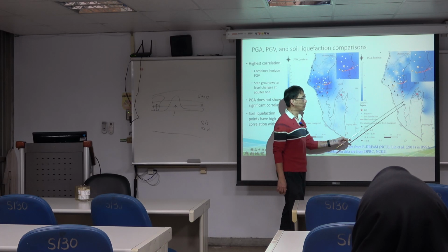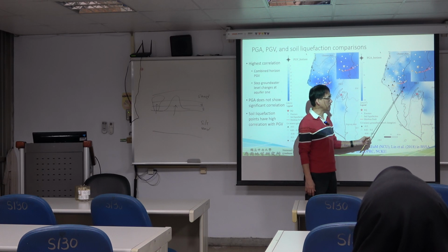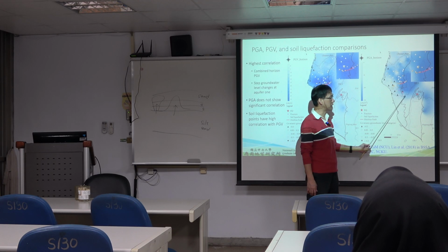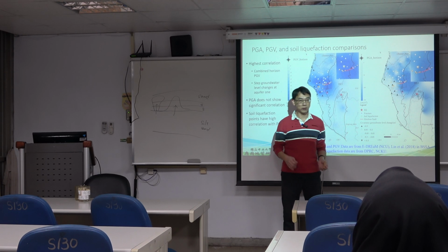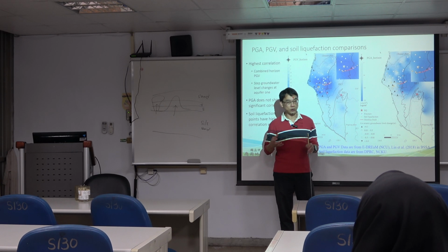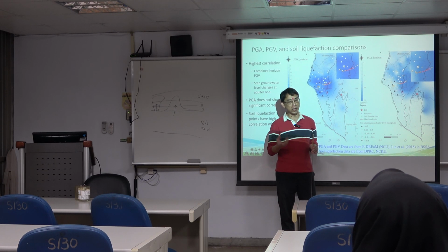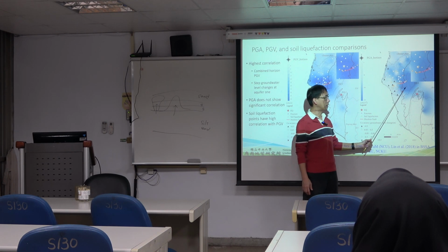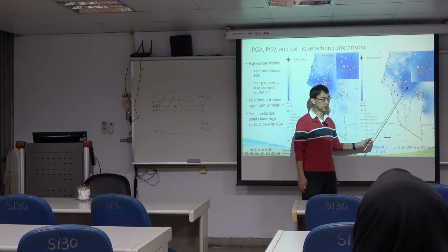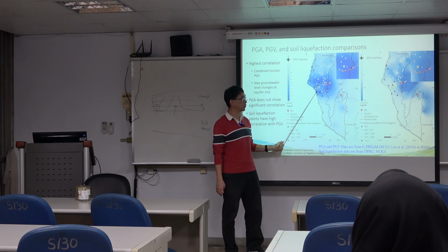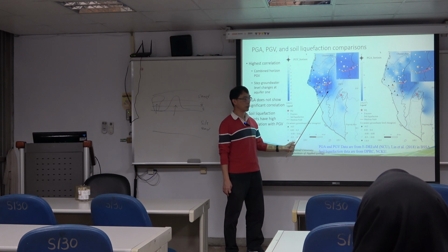But when we take a look at the ground level response and liquefaction points, we will find that they seem not consistent. We can imagine that commonly when the energy is stronger in a place, we might see more damage or more response. But the ground level response is not consistent with the PGA. But when we compare to the PGV, they look more consistent.